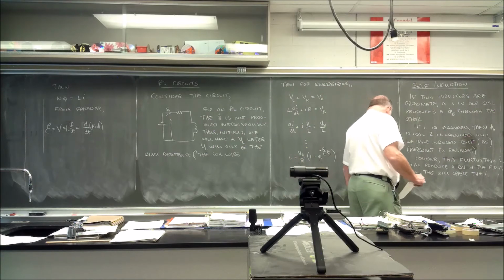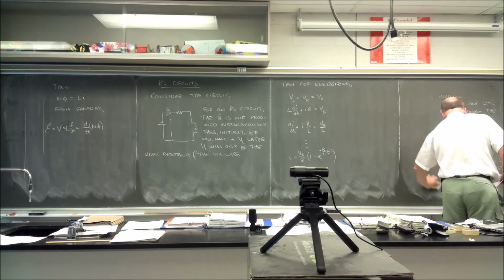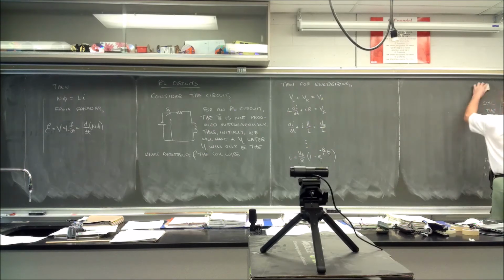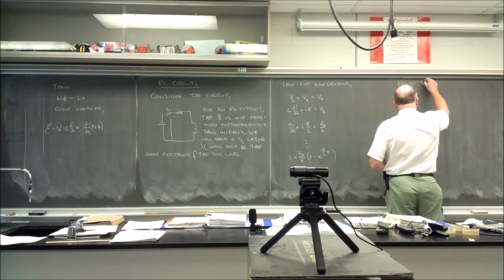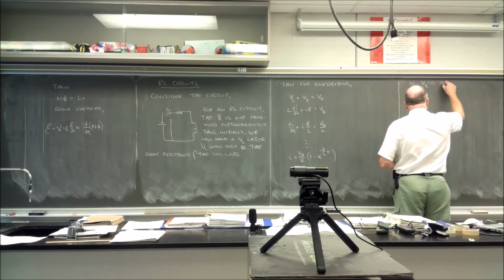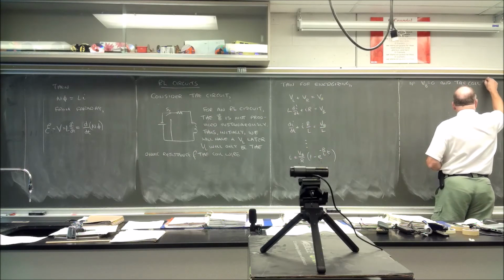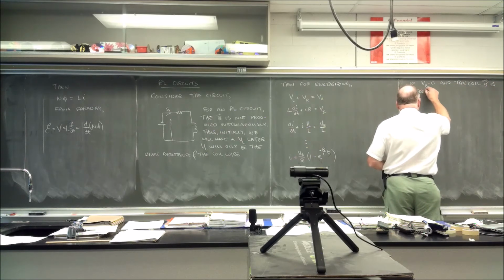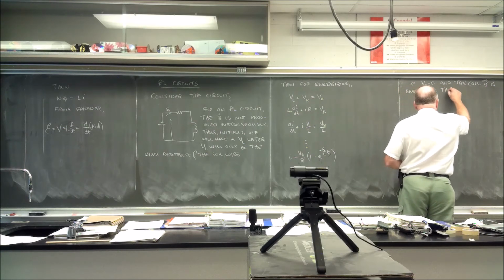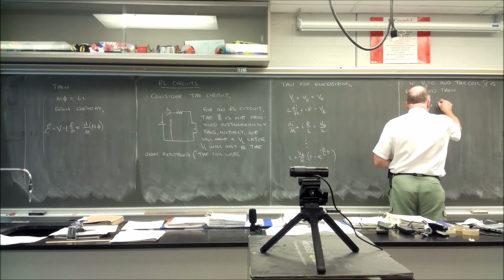If we turn off the power supply and short the wires, it goes the other way, in which the coil tries to maintain the field. If V sub B equals 0 and the coil magnetic field is energized, then we have L di/dt plus IR equals 0.